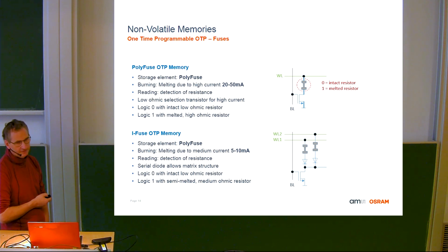To optimize this, you can also reduce the current that you melt with. And there's always a change in resistor values. The higher the change, typically from a few ohms up to a few kilo ohms, the easier it is to build a comparator. If you reduce the current, you could change it from 100 ohms to a kilo ohm, but then you need a comparator somewhere in the middle, 500 ohms or something like that, because you always need to distinguish whether this is higher or lower.